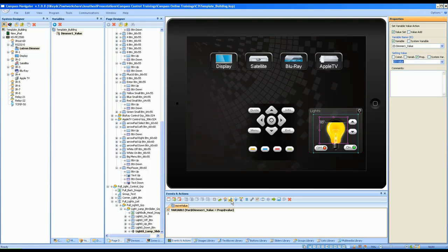However, say that we did that shared controller variable property and multiple iOS controllers were manipulating the value of that variable, well then that would mean that every time that variable is manipulated, the RS-232 command is sent, and so you could have multiple commands being executed at the same time to the single device that is the Lutron or whatever device you're controlling there, and that could of course slow down the system and that sort of thing.